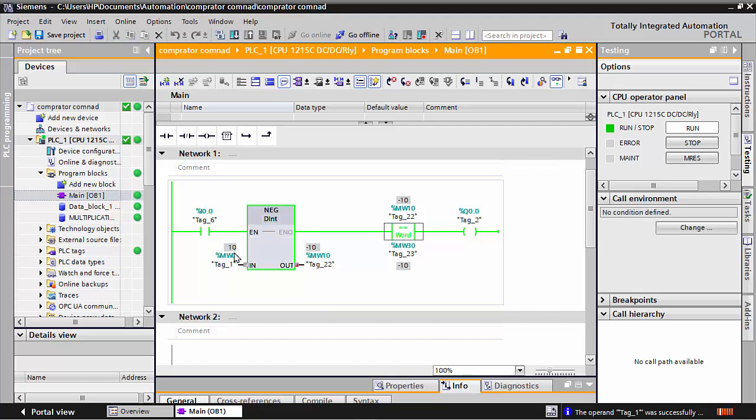See, when I put it here plus data 10, it changes the polarity to minus 10. And what I say, give here to this data register MW10 minus 10, and when my data register minus 10 equals minus 10, my Q0.0 has to be on.